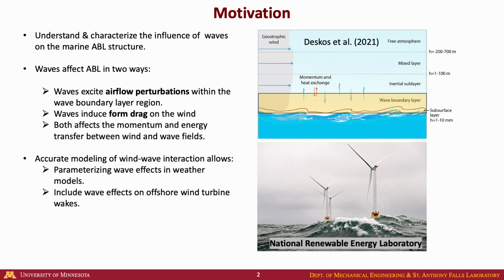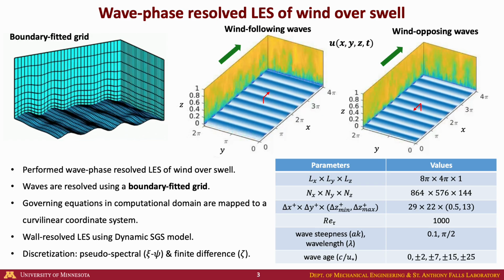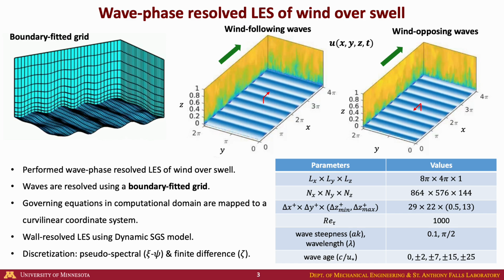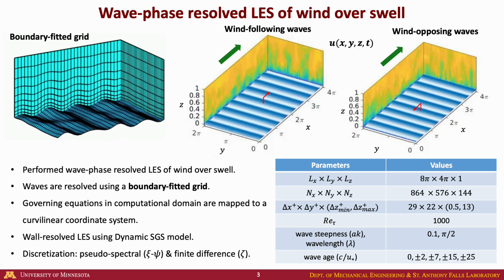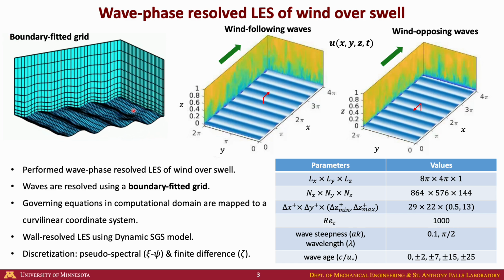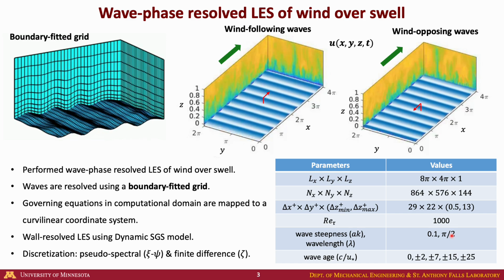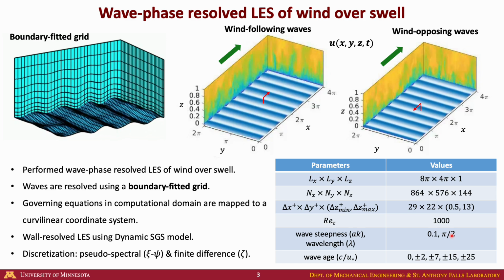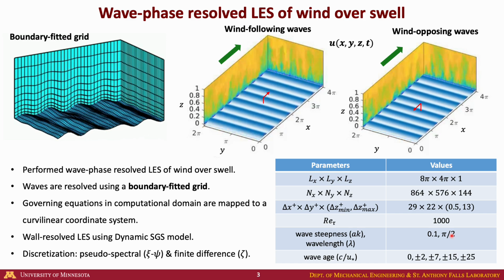offshore wind turbines. In this work, we study wind-wave interaction by performing large eddy simulations of wind over swell. This is a phase-resolved LES where we resolve the wave phase information using a boundary-fitted grid as shown in the top left video. As a result, at each time step, we map the governing Navier-Stokes equations to a curvilinear coordinate system that follows the wave progression.